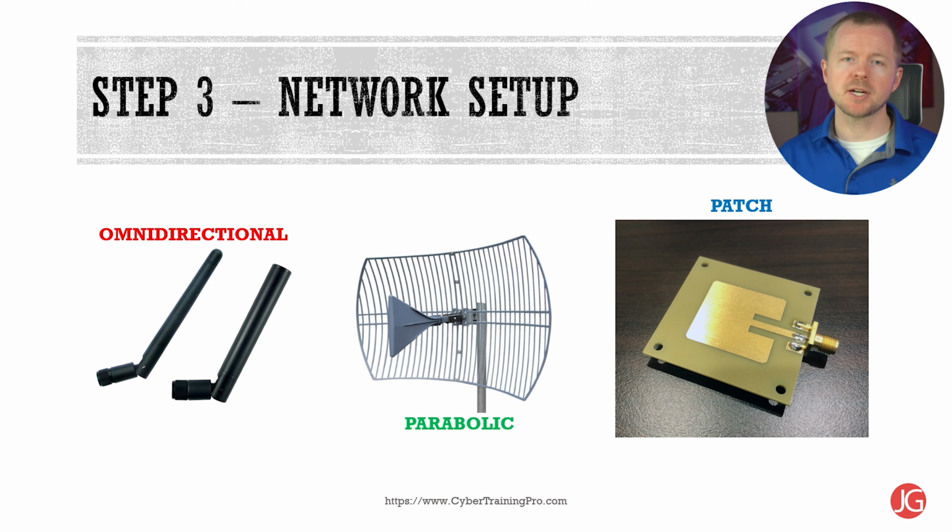Unidirectional antennas are directional antennas that send the signal in one direction. Common types include parabolic antennas, like a satellite dish, and Yagi antennas and beam antennas are 2 more types. Patch antennas are flat plate-shaped antennas that generate a half-sphere beam. These are installed on a wall, and they're really good at keeping the signal inside of a room, and they don't transmit the signal out the back of the antenna.